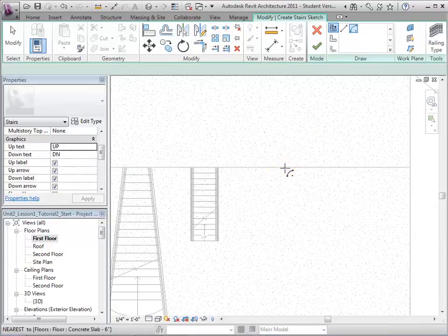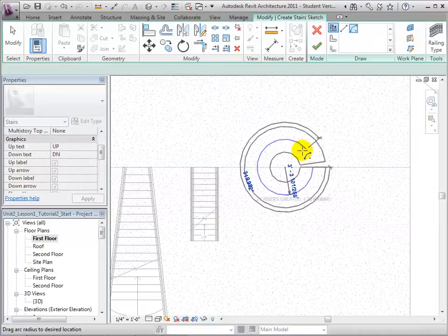However, Revit will not allow us to place a run line on top of another run line. Therefore, once 360 degrees is reached, the direction of the stair changes, or the riser count starts over. Essentially, the steepness of our stair type is too shallow to make a complete spiral.